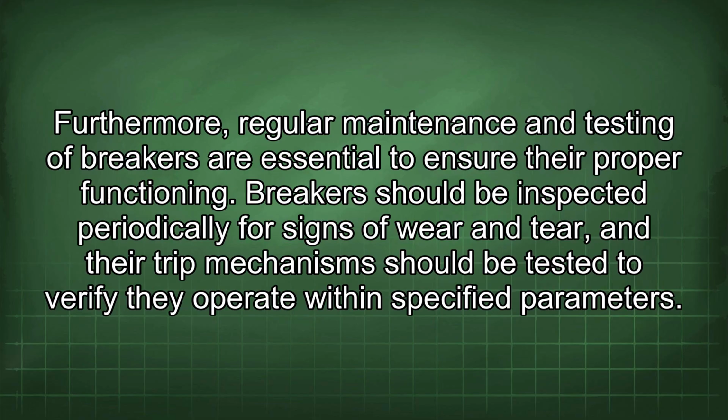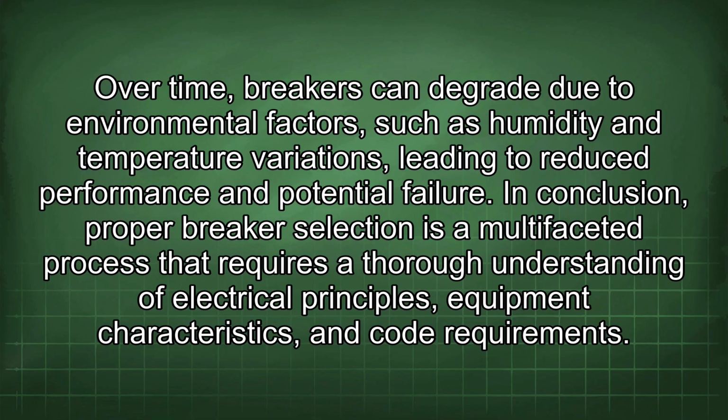Furthermore, regular maintenance and testing of breakers are essential to ensure their proper functioning. Breakers should be inspected periodically for signs of wear and tear, and their trip mechanisms should be tested to verify they operate within specified parameters. Over time, breakers can degrade due to environmental factors such as humidity and temperature variations, leading to reduced performance and potential failure.